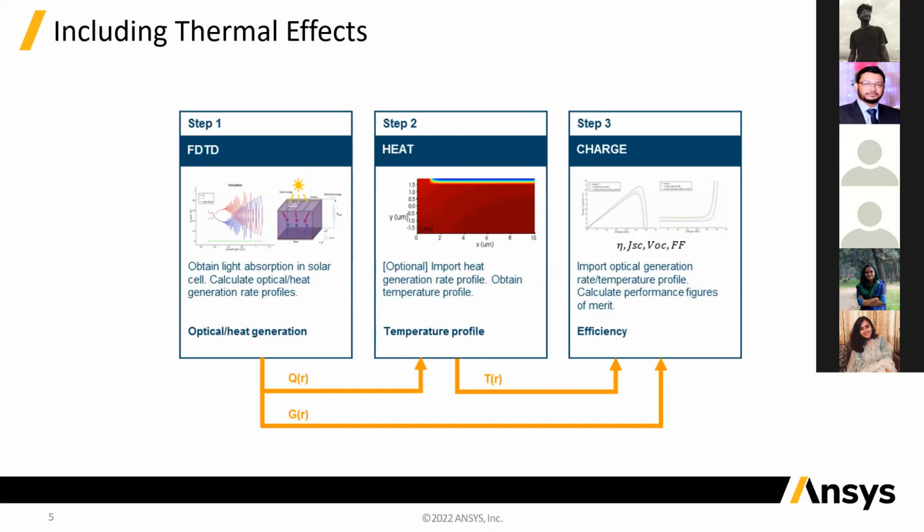Yeah, no problem. That's a very good question. And yes, if applicable, stack can be a way of doing the optical simulation of your solar cell as well. Like I mentioned earlier, as in any other case, when you're designing, stack would be nice. But in the end, it's always recommended that you do a final FDTD simulation as a sanity check, checking it against something that's accurate. But yes, stack will give you a good starting point.